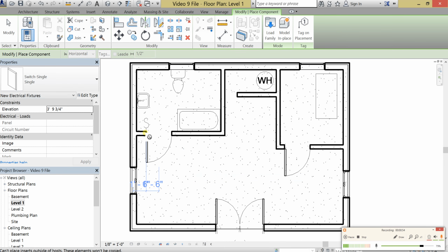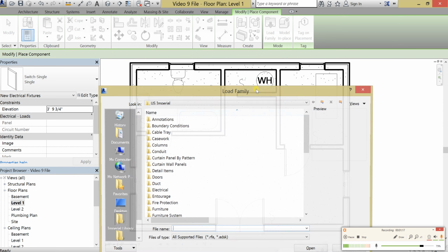And if you think to where you live, typically switches are closest to doors. So when you walk into a room, there should be a switch greeting you. So I've applied a few switches. Let's say though that we wanted to be able to control the lights from 2 switches. Then we don't want to use a single. Instead we want to use a 3-way switch.